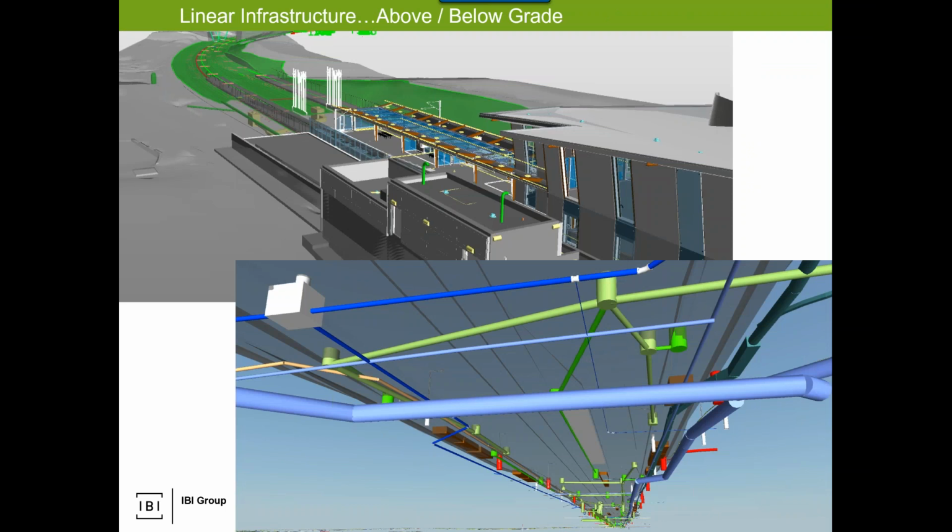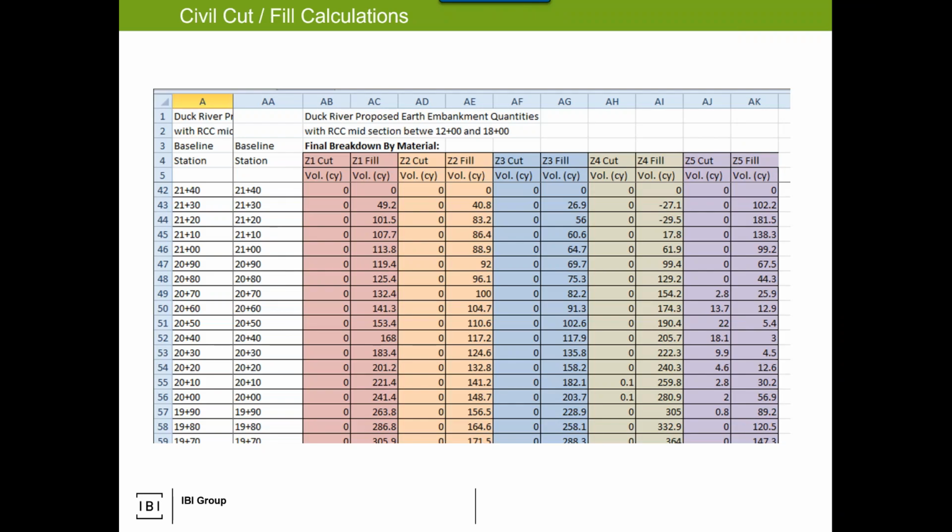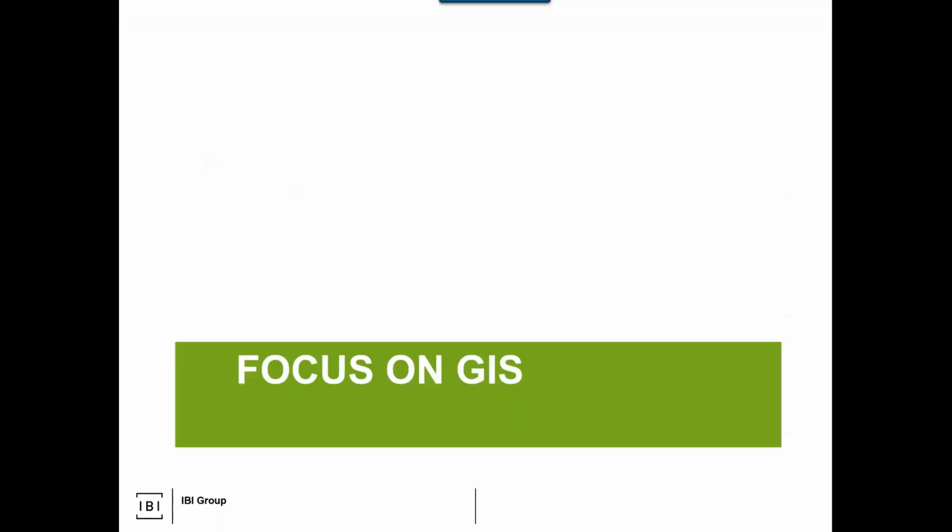Are we using Civil 3D, and to what extent? Who's defining the piping catalogs? How are we sharing those catalogs? Keep in mind those Civil 3D data shortcuts and how those DSPs are being stored, shared, and authored from. Are we modeling just to visualize? Are we going to try to pull asset management assets from these components to bridge into asset management systems? Are we looking to do cut fill calcs? So are we going to have to expose surface models or subsurface models and have those integrated into tools like Navisworks?